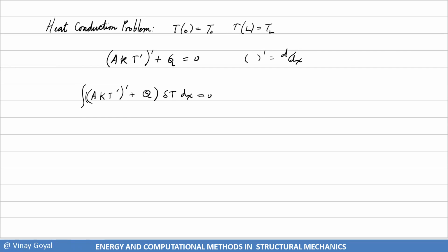Now I'm going to integrate by parts to bring the same number of derivatives on the primary variable of interest into del T. So I'm making the residual orthogonal to the space of virtual functions del T, because this is really a virtual change in T. Then I'll integrate by parts very quickly, in one step, with very little pain, and we get a lot done.